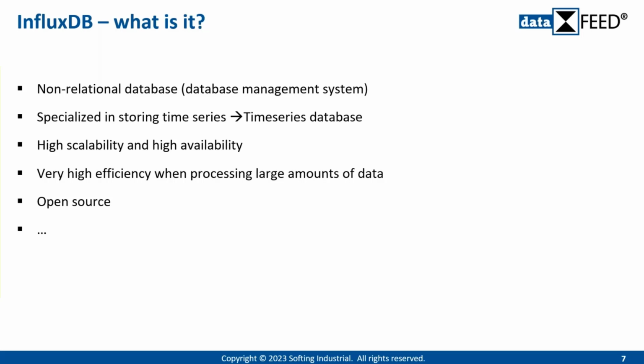This brings us back to the data which we have in a production environment. Process data typically are time series. You store the temperature of your complete day from your production for later control if everything was okay. It's a time series. So this is why a time series database is, from my personal point of view, an ideal database for collecting process data.